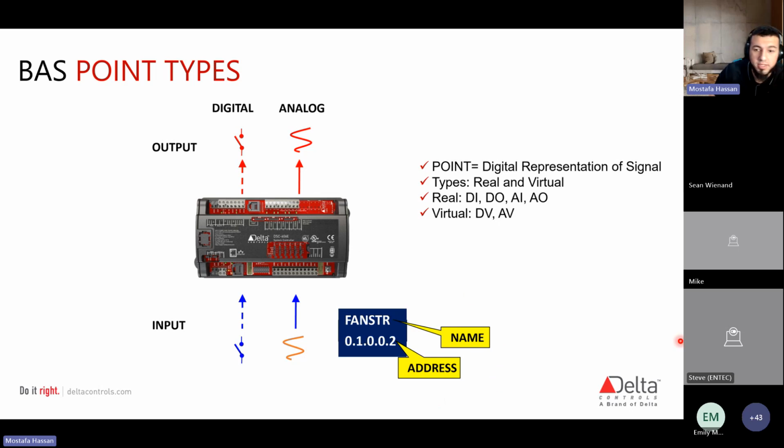In a BAS program, there could be dozens of virtual points that the programmer uses to represent set points, time delays, statuses, conditions, intermediate signals, etc. These points take programming time, but they don't actually require an input or output at the terminal of the control. Wiring of the device is not necessary. There is no actual physical presence to it.